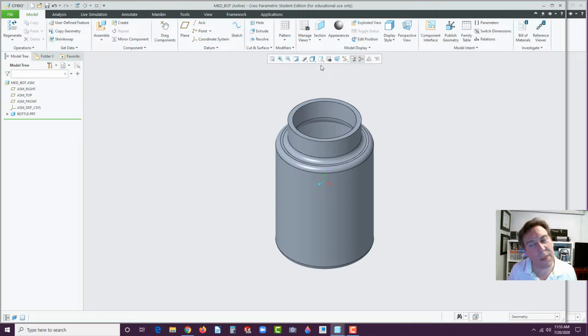Do you need to do that? Kind of. Unless you're a very advanced user, I haven't taught you how to section when something's not on the section in the view. So what would happen if you didn't do that, if you missed that step later on, and listen closely, later on in your drawing, when you go to try and create a section view of this bottle, if you didn't lock that in, you will not get the section view. And then you're going to have to sit there and figure out how to get it. And that, I've had students just not have the time to do it. So just be aware that step, choosing default instead of automatic for the placement, is going to save you a lot of time because you won't have the issue then.